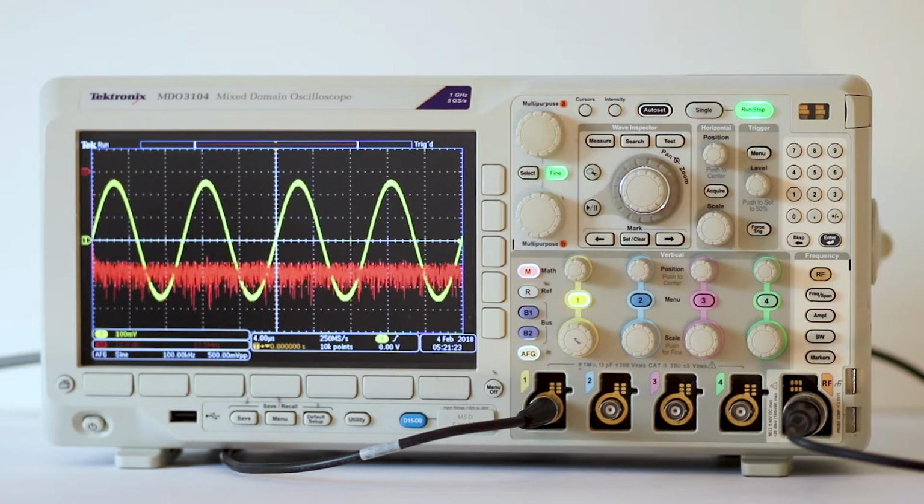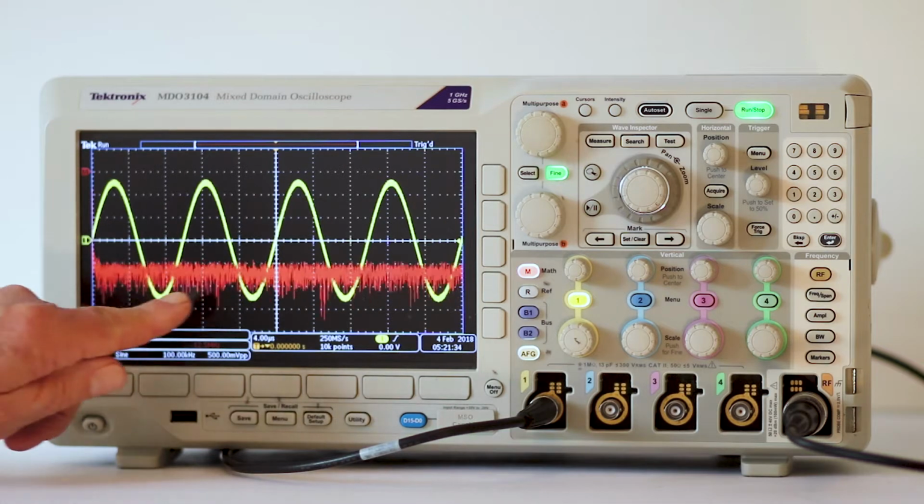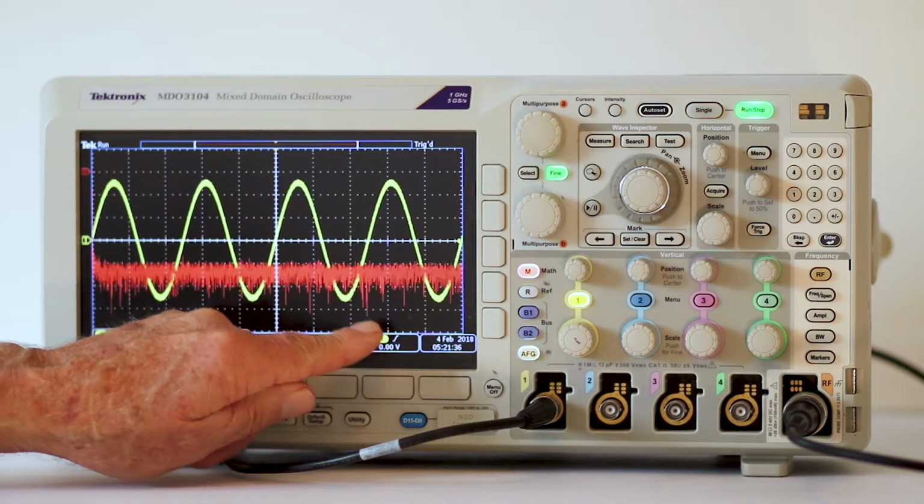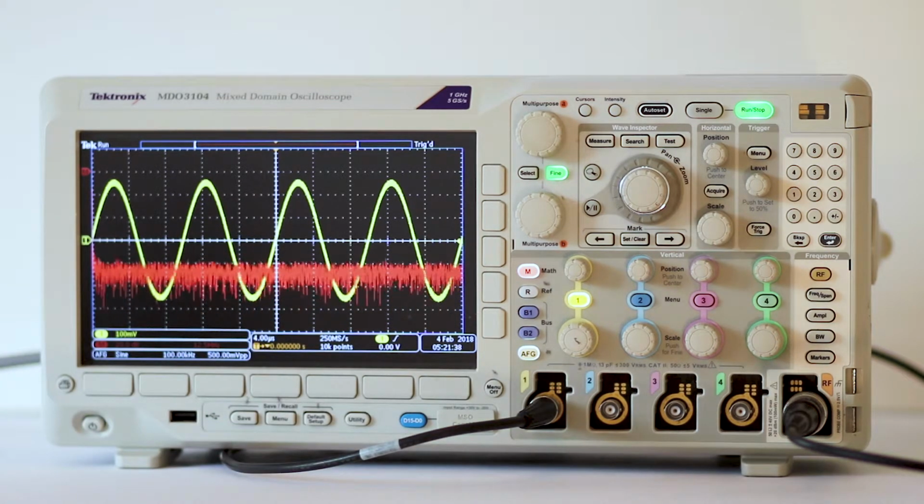The only other energy that is displayed is the noise floor, which appears as an irregular, roughly horizontal, fluctuating line at the bottom of the screen. This represents the wide-spectrum thermal noise level, which obscures any signal that falls below it. It does not represent any malfunction of the equipment, but is just a consequence of its sensitivity to random charge carrier motion.